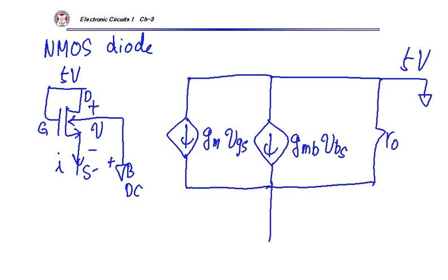Yeah, this is my small signal equivalent circuit. Okay. So here, see, let's see. This is my VO node, right? Then what's VGS? My VGS equals, this is AC 0. In the small signal equivalent circuit, the 5 volt DC is AC 0.